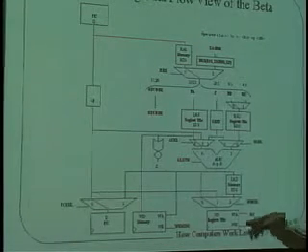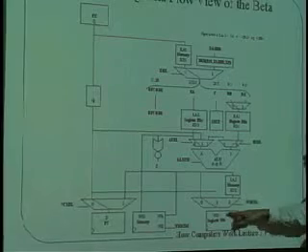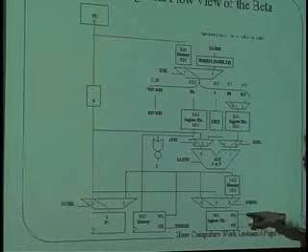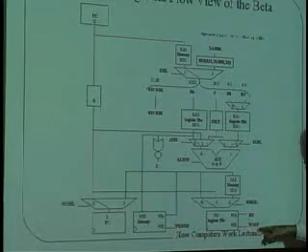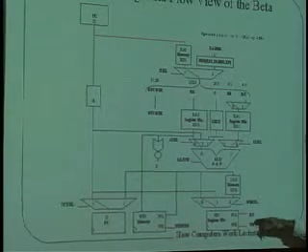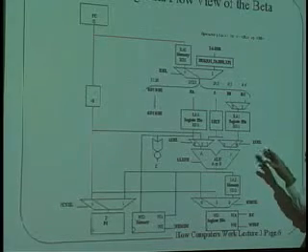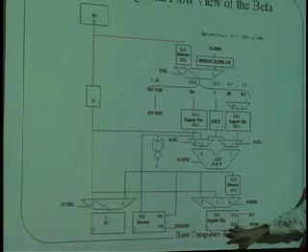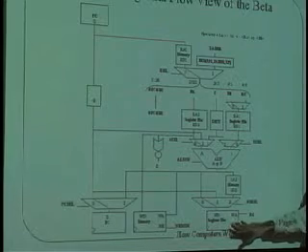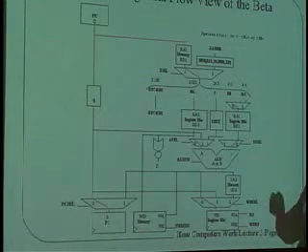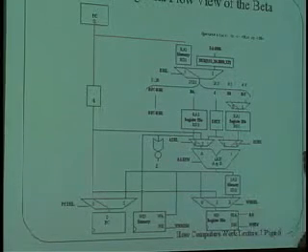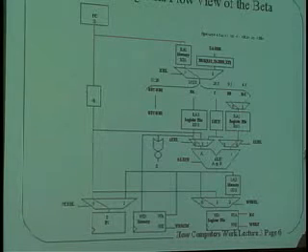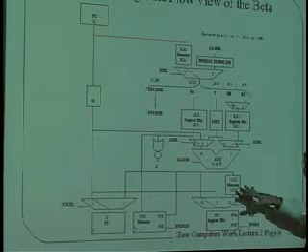And if this bit is a 1, then the register file, when it gets the data and the address here, will write that result into the register file. And the reason that we need this write enable is that some of the time we're going to be doing operations where the register file is not the destination, and we won't want to write the register file. So this is just like that little tab on a disk or something that says whether or not you can write the disk, right? This says whether or not the register file should be told to do a write. And so that's basically how it works.